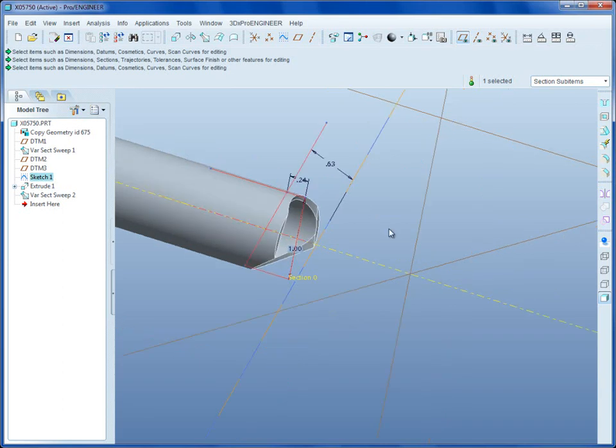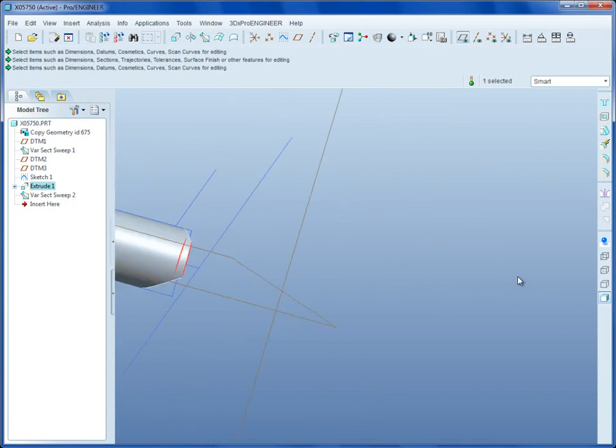And then when I throw it on the drawing, I have this edge, this curve here, that I can dimension to the overall length of the tube as cut, the full length. I then have a pair of curves here that I can put an angle on to show the angle of the notch, and then the notch itself, which is done with the extrude to cut the end to the appropriate length.